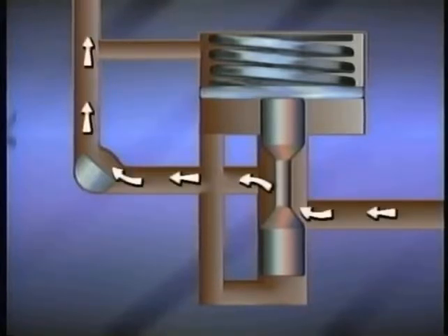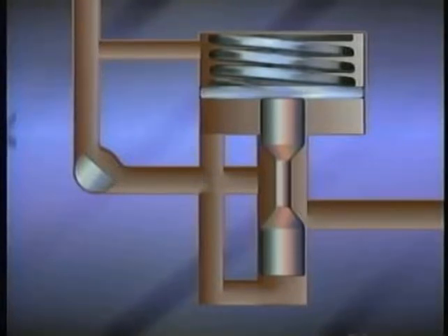Fluid enters the valve through the inlet, flows through the throttle, and passes through the outlet to an actuator. Fluid pressure is sensed in the chambers below and above the spool. The actual flow control is accomplished by the throttle. The throttle is simply a cylindrical-shaped piece of material with a notch cut into it, which reduces the area through which the fluid must pass. The throttle can be adjusted to provide the proper flow rate through the valve.